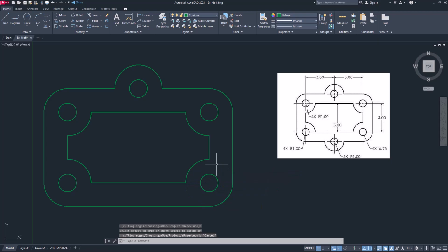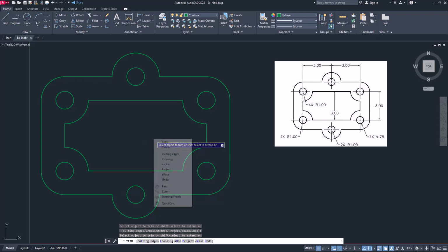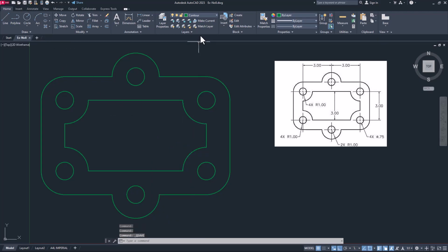now save your drawing. I hope, student, it makes sense to you. Now let's mirror the upper circle part. MI for mirror. Select this part and choose the midpoint. Okay. Now let's trim this part. Okay, and this part. Now save your drawing. Now let's give the center lines.